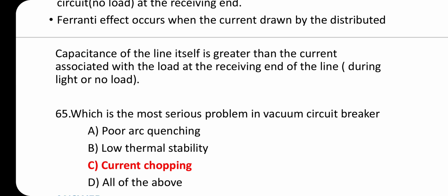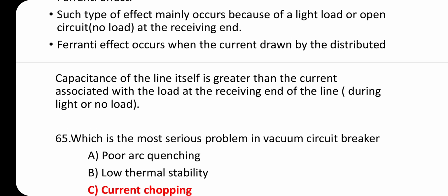This capacitor charging current leads to a voltage drop across the line inductor of the transmission system, which is in phase with the sending end voltages. This voltage drop keeps on increasing additively as we move towards the load end of the line, and subsequently at the receiving end, voltage tends to get larger than the applied voltage, leading to the phenomenon called Ferranti effect in the power system.